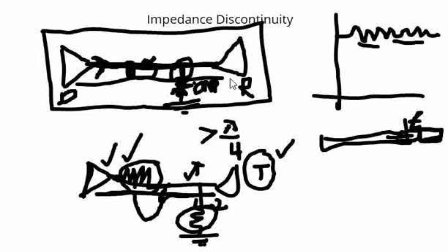So, to summarize some of the points, ensure that there are no vias. If vias are required, use vias which are basically micro vias rather than a full through hole via, so that you can eliminate some of the discontinuities. And if you have to use a full via, you can use a costly back drilling technique where some of the via stub is cut off from the bottom, which is another way of reducing the impedance discontinuity.